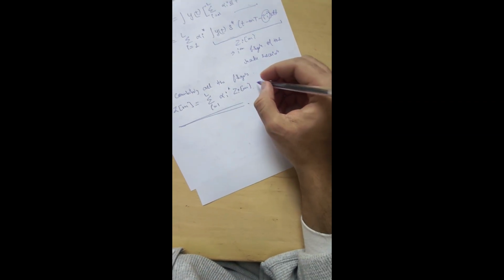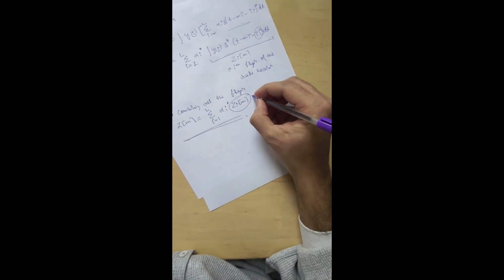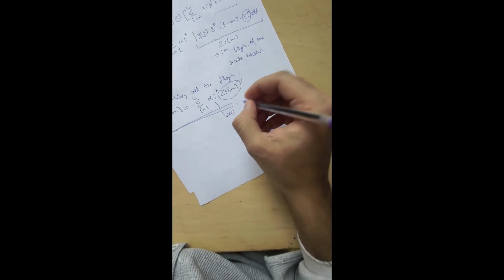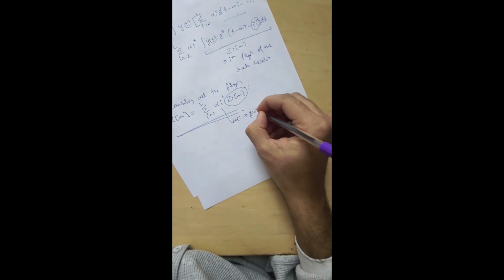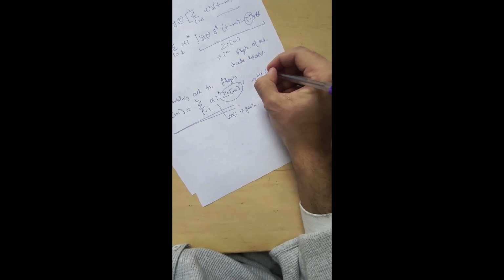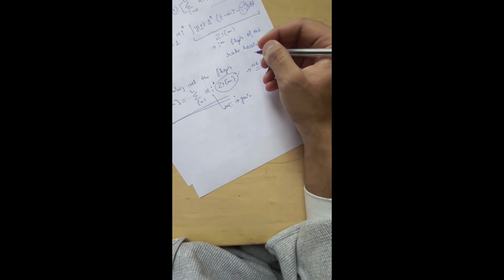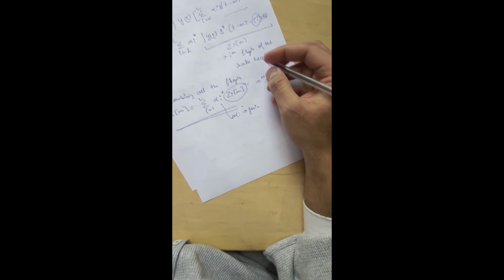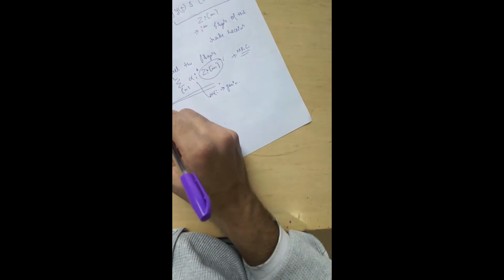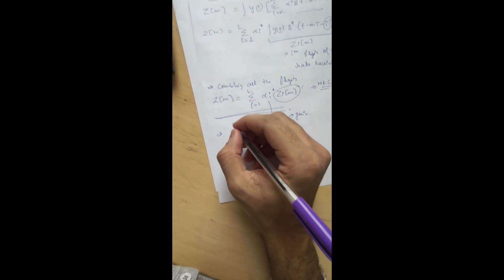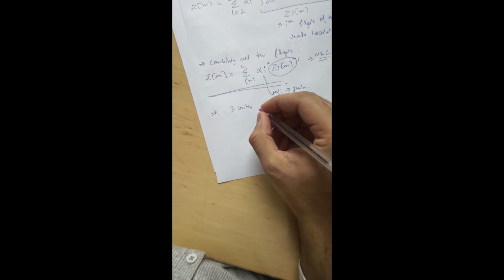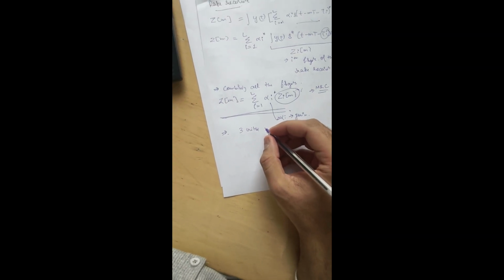Here we weigh each finger by its conjugate gain alpha i, and this is known as maximum ratio combining, and it ensures the strongest path contributes the most to our decision. Also, there are three critical points that I wanted to point out for this derivation.